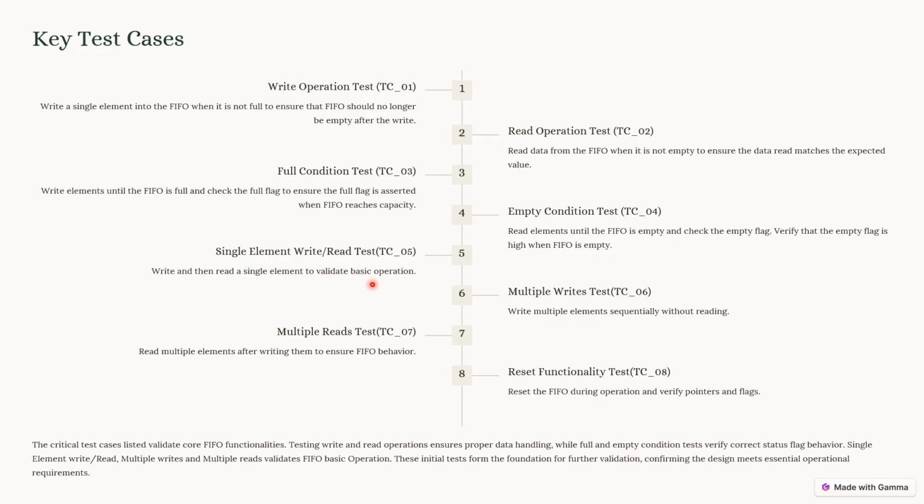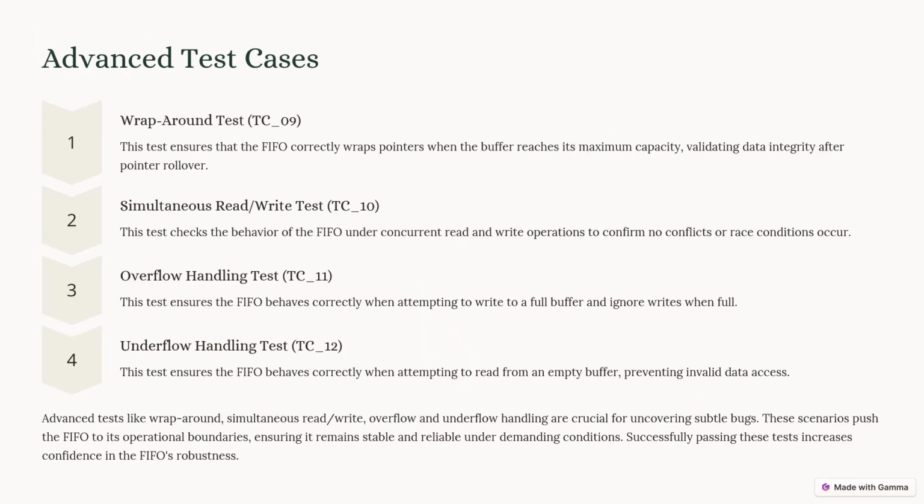Single element write read test. After that, multiple write test without reading, and after that multiple reading of the data which is written in the FIFO. After that, reset functionality is tested so as to check whether the proper initialization of the FIFO occurs or not. Apart from key test cases, there are some advanced test cases that we will be verifying through our test bench.